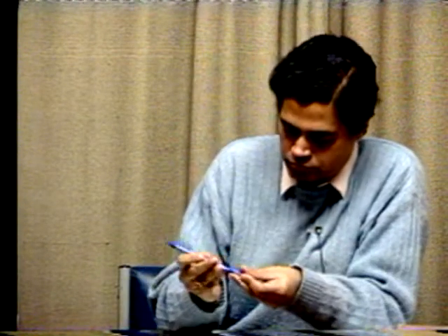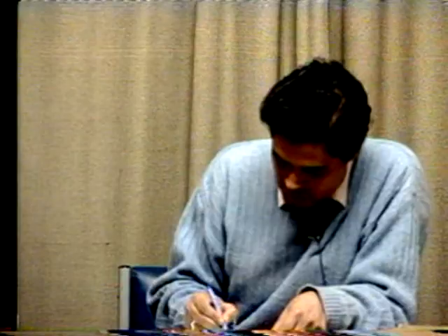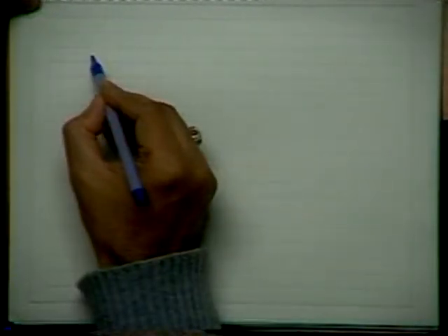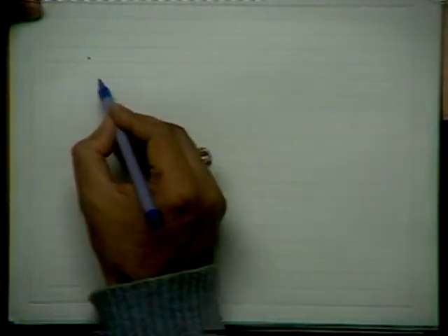So you know that these frequencies are quite high, and the kind of isolation which is needed cannot be achieved by junction isolation. Junction isolation is not sufficient to do that. So I have to find out certain other alternatives for that. So what people do, let me just show you one thing. As I told you, suppose, say, bipolar technology, let us consider that only.